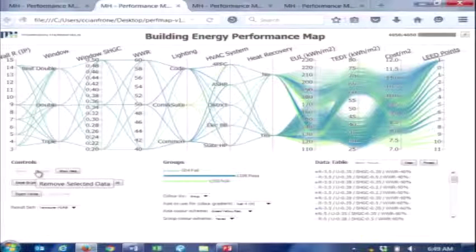The reality is most high-rise concrete construction, when you take into account all the thermal bridging, has effective R-values in the range of 5 to 10, unless it's exterior insulated, which we don't see a lot of out west. In fact, even in Ontario, a lot of towers are being built with window wall systems, so not very good performing envelopes. And we have window performance, window-to-wall ratio, mechanical systems, ventilation heat recovery.